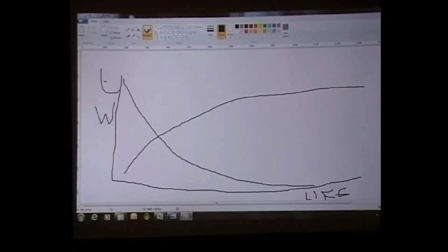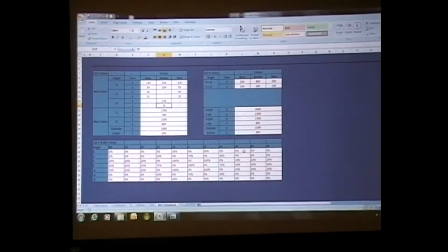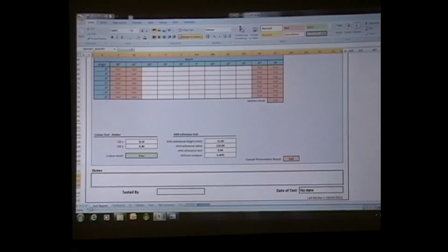LEDs are really expensive still, but they can take as much power. You can get 10 watt LEDs now. Well, something like this, you can't power 360 degrees with an LED because they're very much directional lights. So you'd need a tower with several of them around. With 10 watt LEDs, you're starting to get up to 40, 50 watts. Well, an incandescent beacon bulb is a 55 watt one. So anyway, that's a nice way to give the user some control of what is entering on all of this.